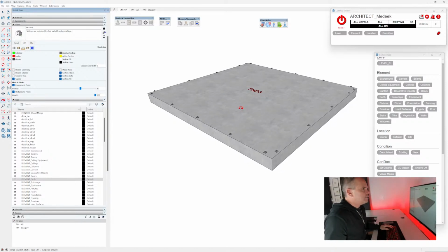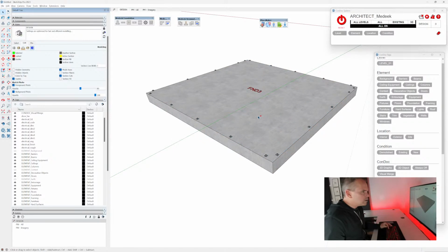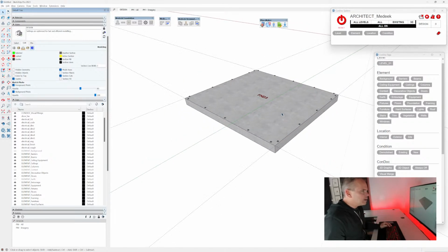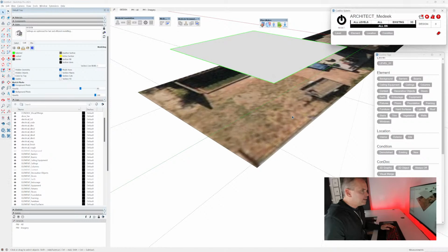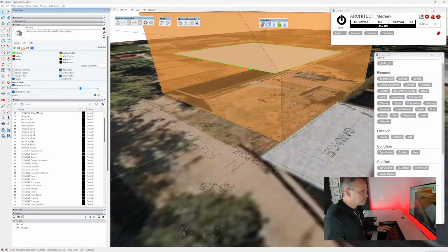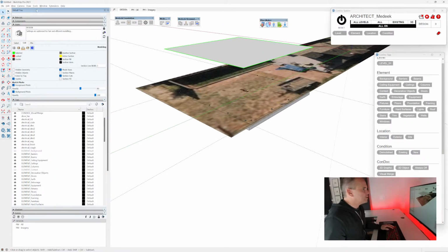And this is where, every time I hit reset, we're getting back to this lot. So perhaps at this point, I'm going to hit undo. Oh yeah, and I'm going to hide this. I'm going to draw this rectangle like this, and then I'm going to make it a group and scoot it straight up on the blue, hit reset. There we go. All right, so now I'm going to drape this. I'm going to go to Tools, then Sandbox, and choose Drape onto here.